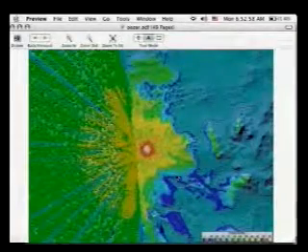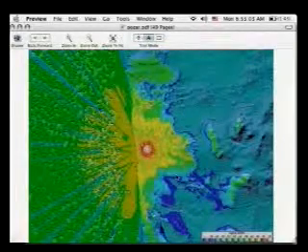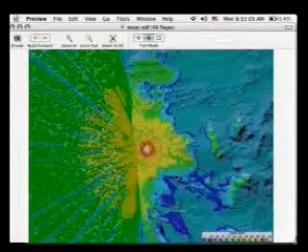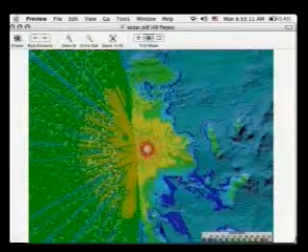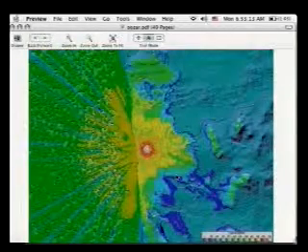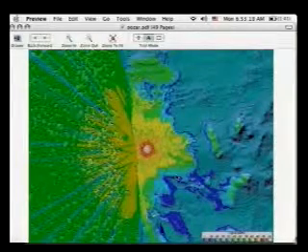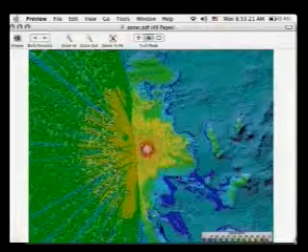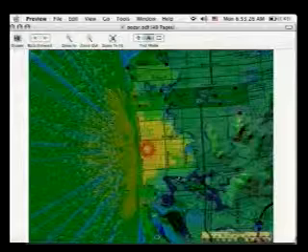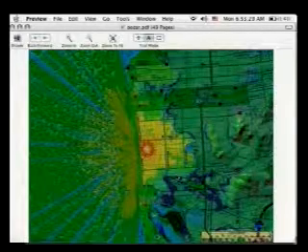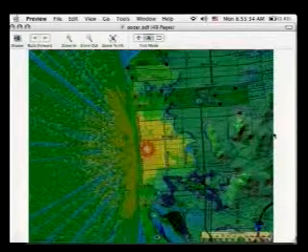This is an example of an output of the Radio Mobile program. This is actually my transmitter, my access point, out in the Sunset of San Francisco. To the left, you see the Pacific Ocean. To the right, that's San Francisco. You can see that the red is the largest signal strength, and the purple or whatever is no signal strength. You can tell there are some mountains or hills to the right there. Just to give you some scaling, you can overlay, I think it's Yahoo Maps or MapBlast, images on this to get an idea of the scale. So you can see Golden Gate Park up there.